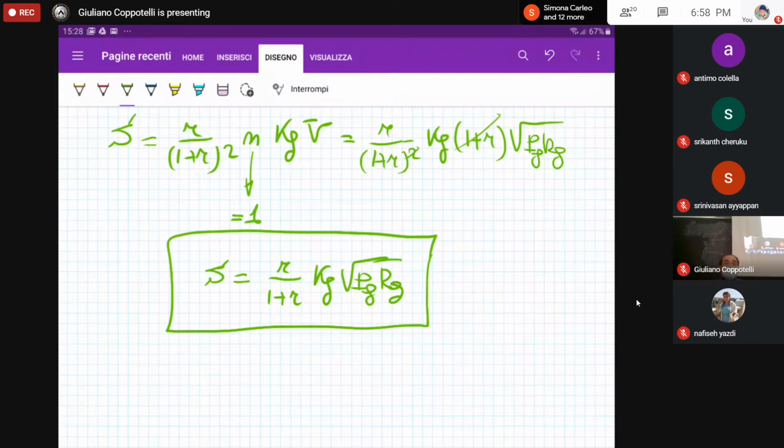Okay, so that's the reason why when using two strain gauges, we are using legs number 1 and 4. That's because the sensitivity is higher than using 1 and 2.